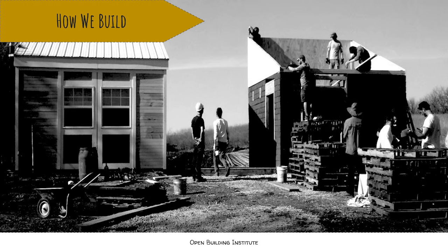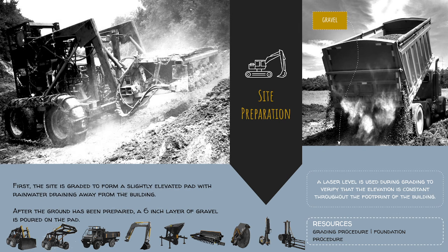That's the structure that has the aquaponic greenhouse that we formerly used. We're doing wood cladding. These are unstabilized blocks, so you've got to protect them from moisture. What do you do? So that's, for example, our tractor soil pulverizer in action. We actually did mix a bit of cement in there and munched it up and threw that into the brick press to get stabilized bricks with not high quality controls. You know, some parts might have more cement, some parts might have less. You can probably recognize that smoke from all the cement, like we were burning it up last night. So that's what you do.